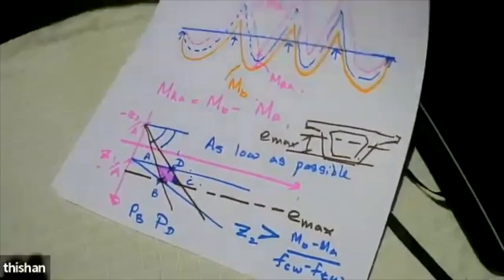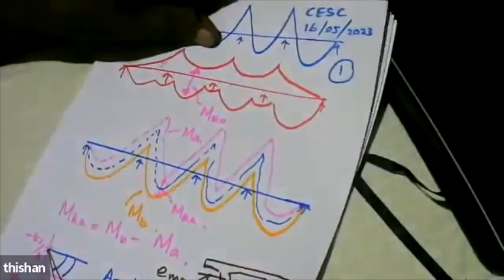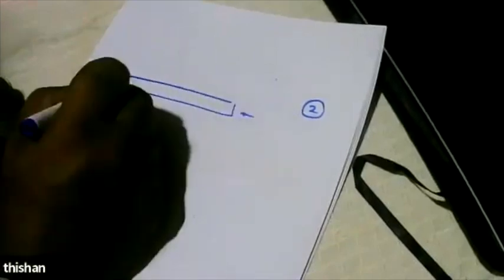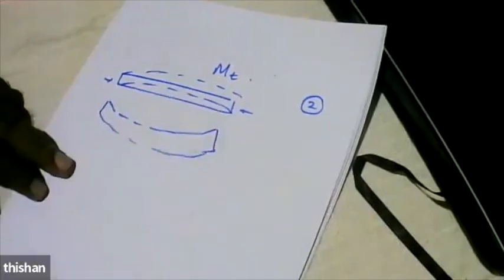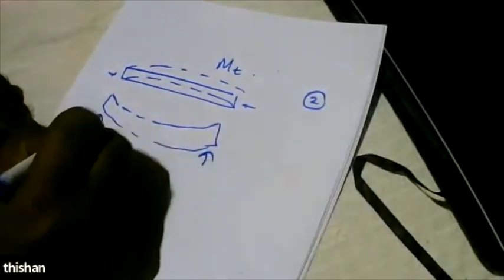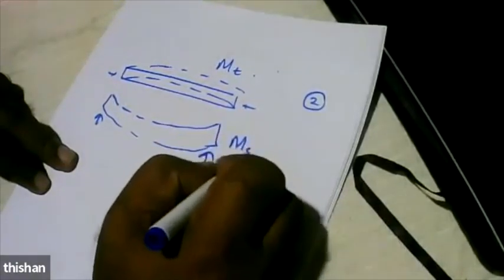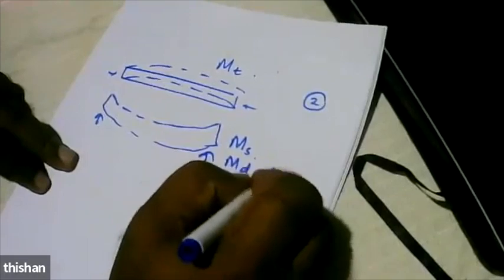So basically, for the simply supported case, we have a beam subjected to prestressing. Then it will move up like this. We call it moment at transfer. Then it will bend like this when it is subjected to the maximum loads. And we say it is the service condition where MD and ML will act.